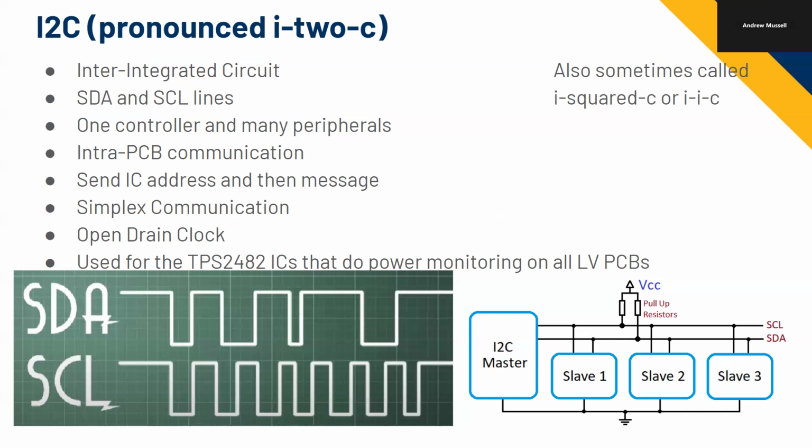We have the clock ready beforehand, so why do we need the clock? UART is much slower than this, so we can just read, and even if there's drift, we probably won't drift far enough to cause an error. But with I2C, you can communicate much faster, so you need something that helps you time better to know when to read. Otherwise, you might get out of sync and end up reading a bit too late, or reading on a transition.